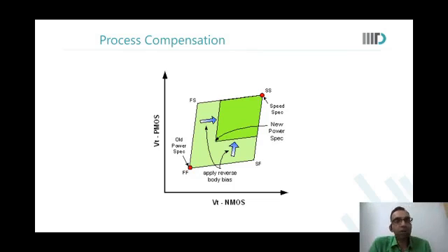So you can apply whatever amount of forward body bias or reverse body bias that you want to. So you are talking about here the SOI technology. Yes. The fully depleted SOI, not even partially. If you were on partially depleted SOI, then again you will face trouble because junction would be there. Only in fully depleted SOI, you can actually go to a very large range of body bias voltages. Okay. Yes, sir.